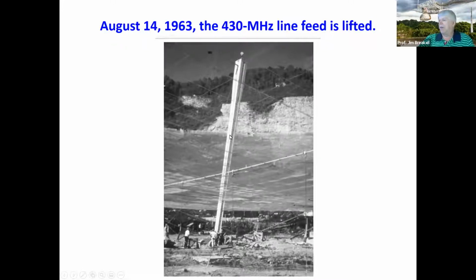And the energy comes out in a very structured manner with certain amplitudes and what's called phases, or time delays. And so all the rays that would reflect off the dish from some distant object, by the time all the rays hit each of these holes and then combine back to this region, they are all combined in focus, just like a parabolic dish would do. But it's a very clever thing that allows the feed to be moved, and you can still collect all the rays, and that moves the beam of the antenna.